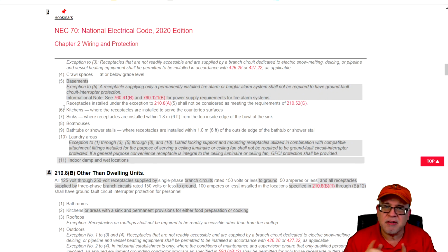And they think that they're not allowed to put the refrigerator on that small appliance branch circuit, when in reality, that's what the code starts out telling you that you can do and requiring you to do. And then it gives you an exception to say, well, if you want to run a dedicated circuit, you can, go for it. But most of the time, we're going to put our refrigerators on the small appliance branch circuit. It's so intermittently used that it really doesn't present a problem. And that's why you're required to have a minimum of 2 anyway, serving the countertop spaces, okay?